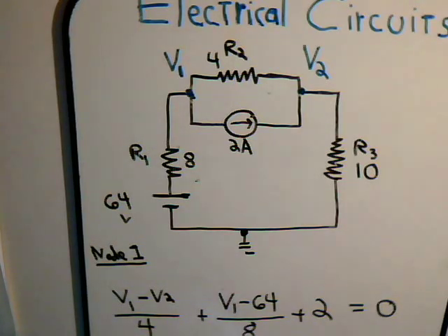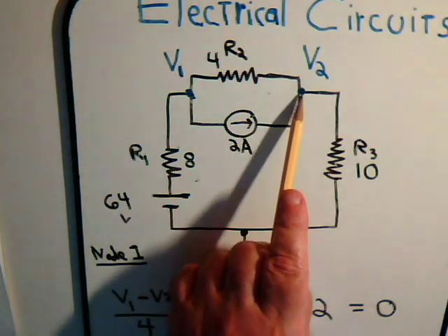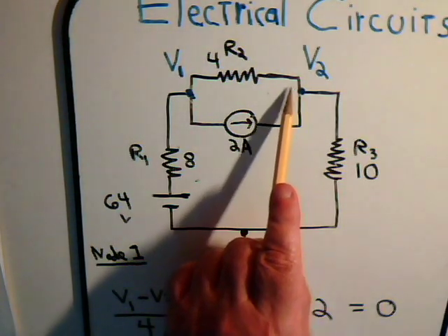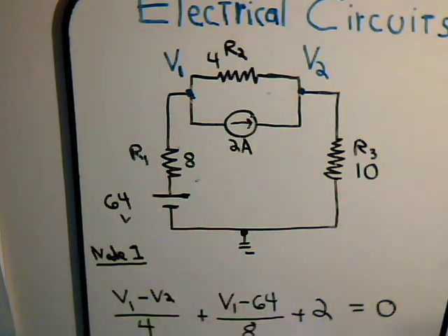When we consider node 2, over here, we're assuming that this unknown current flows away from the node, going in this direction across the resistor. Clearly, both of these assumptions can't be right, but again, we'll adjust for that once we determine the numerical values for V1 and V2, and we'll settle that out later then.